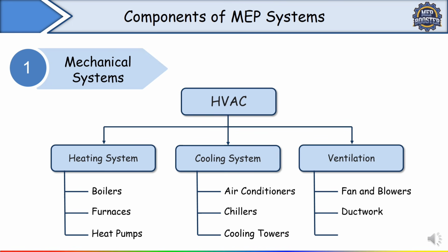The next component of ventilation is ductwork. So different types of duct we are using. Supply air duct we are using to distribute fresh air throughout the building. Return air duct we are using to return stale air from the building. Then, to control the flow of air within the duct and to balance the system, for that we are using the dampers, okay.